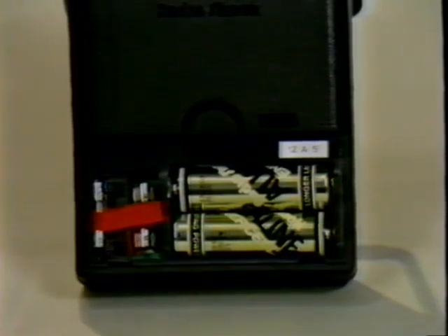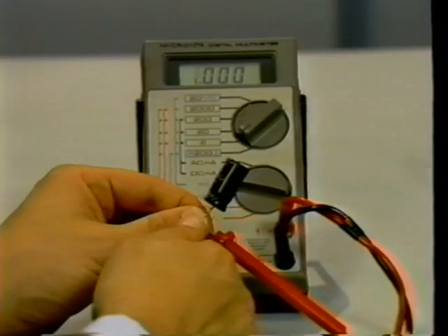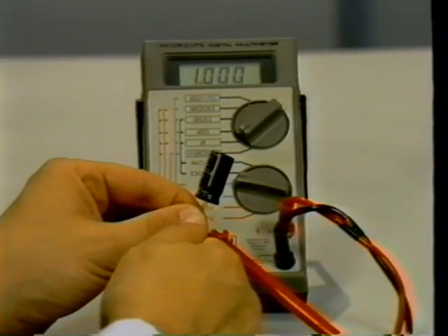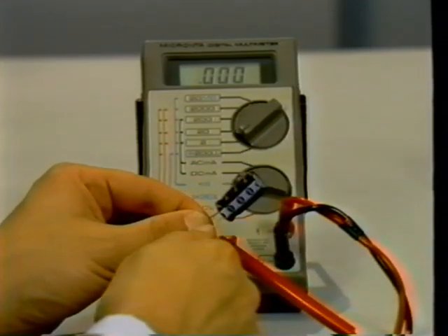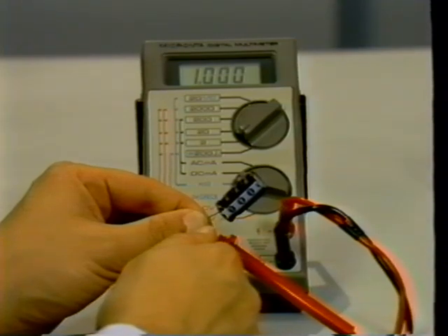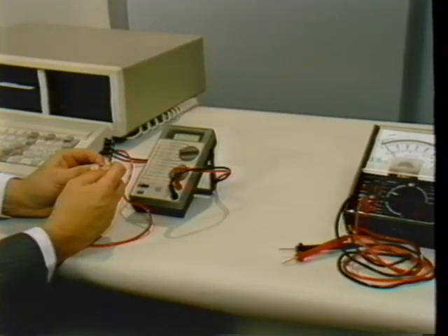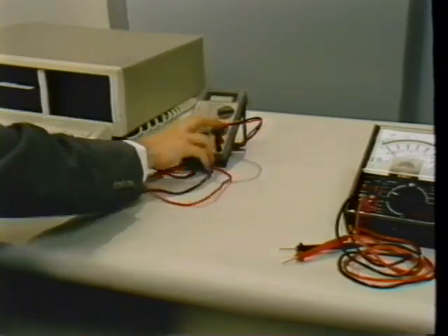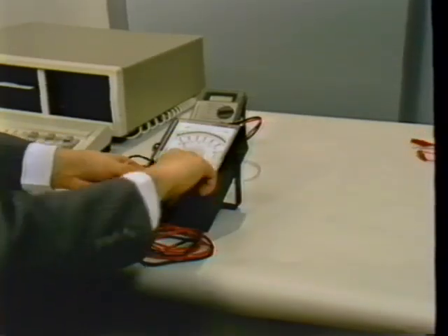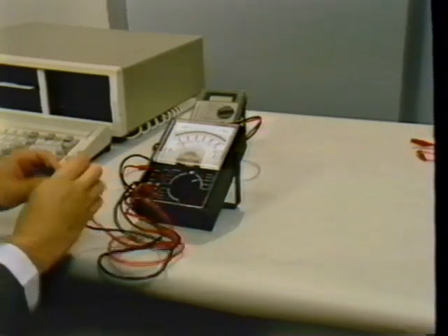One is that it requires an external power source to make readings of any type, while the analog meter needs a power source only for resistance measurements. The other disadvantage to a DVM is that it is not well suited for checking capacitors. It cannot check diodes or transistors either unless it has a diode check scale. In many digital meters, the resistance setting doesn't generate enough voltage to forward bias a diode. Also, the digital scale doesn't reflect varying voltage as well. An analog meter, however, performs these functions easily.